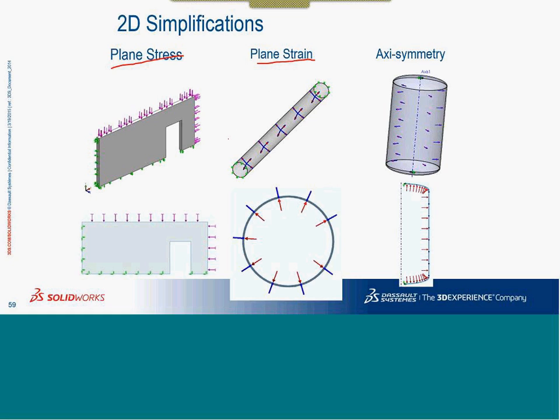And again, if I put it simply, or if I think in terms of plain language, really any long structures, infinitely long, something like this, or take a few standard examples, say a huge dam which has a comparatively longer length compared to its cross section. I would say something like weldments which are represented as beams. Those, if they are to be simulated in the form of a part only and with a consistent cross section, then we can actually use plane strain elements.